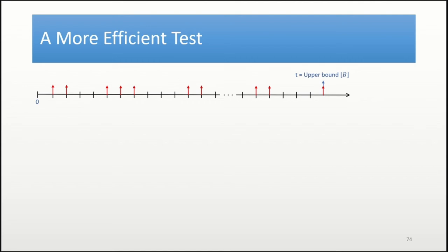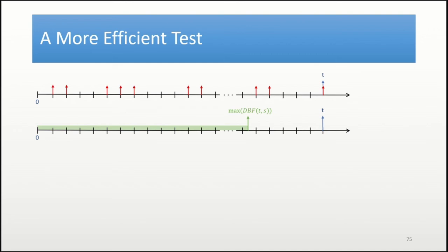In order to determine schedulability, MCQPA considers interval lengths in a decreasing order, starting with the predetermined upper bound B. The algorithm then computes the cumulative processor demand for all possible mode switch instances S belonging to the set S of B, depicted by red arrows in the figure. The maximum cumulative demand seen is recorded for this interval length.